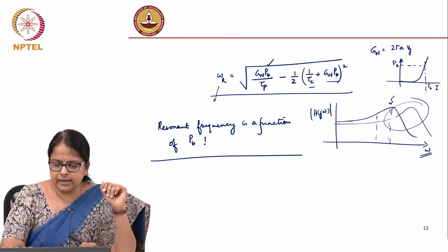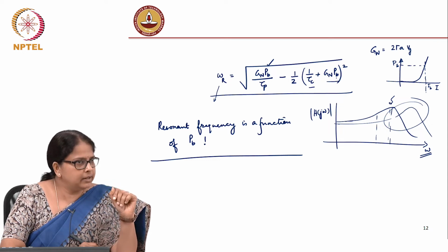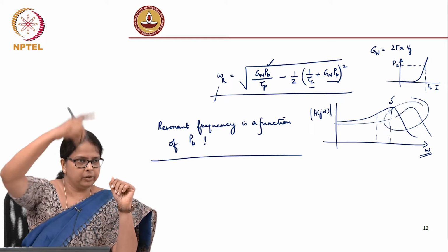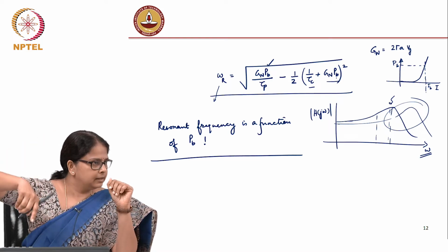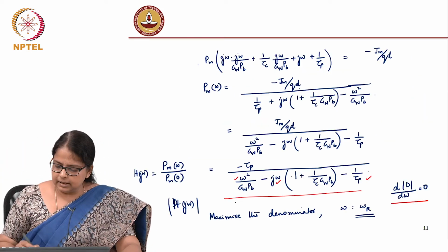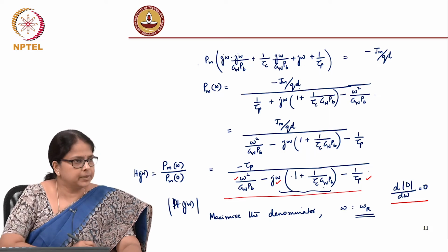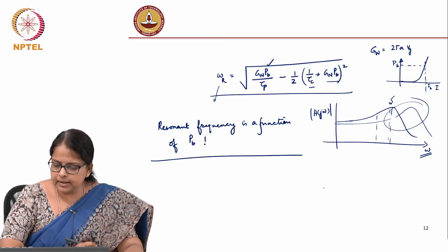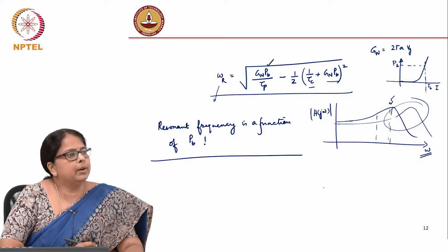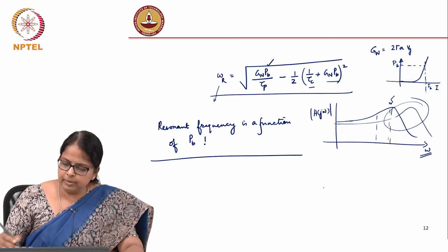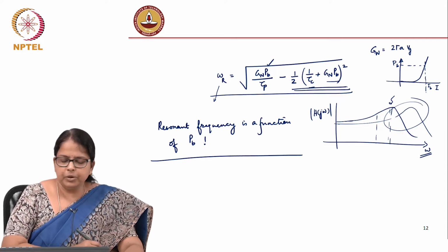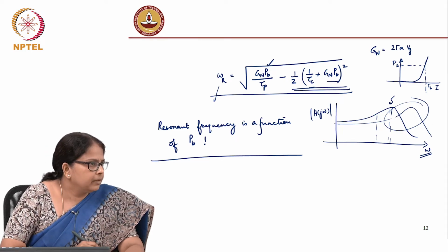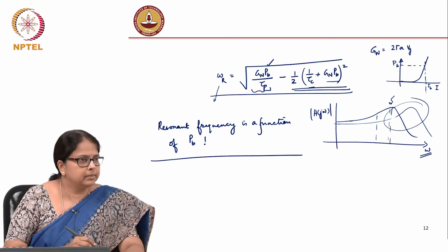So, the point is there is a certain resonant frequency and the system is resonating, but that does not mean the response is going to be like an LCR resonance curve, because there are also these damping terms, these omega terms are the damping terms. Okay. So, if you plot this, it will turn out that when the laser is above threshold, the contribution of this term is going to be very small when compared to the contribution of the first term.